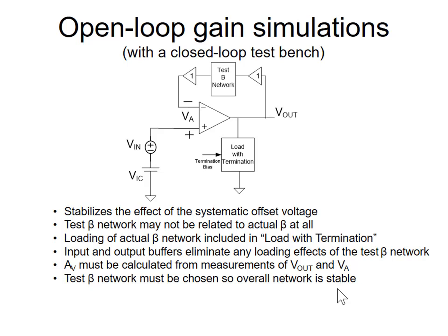It may well be the case that when you start to design an amplifier and you're ready to do some simulations, and maybe your goal is to work with a beta of 1, if you put a beta equal 1 in, it may oscillate even. You may be a long ways away from being correctly compensated. If you try to simulate that open loop amplifier in a feedback configuration and it oscillates, it's not very good.